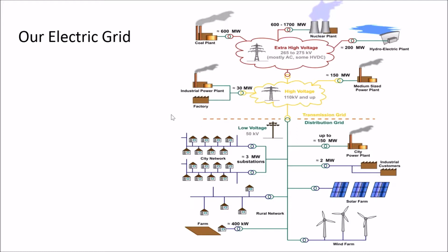But these are real logistical issues on interconnecting distributed solar to the grid: can you, or are you going to overload your distribution circuit? It may be easier to do one 4-megawatt project than to do 100 or 1,000 4-kilowatt projects.